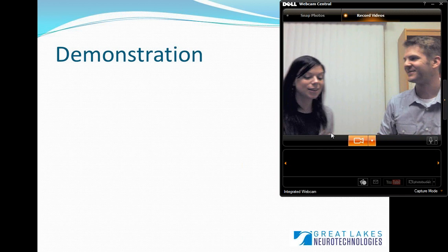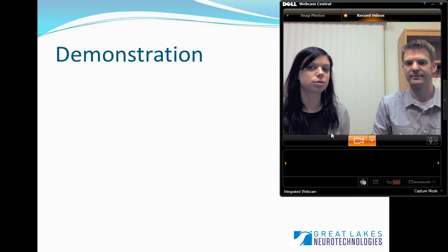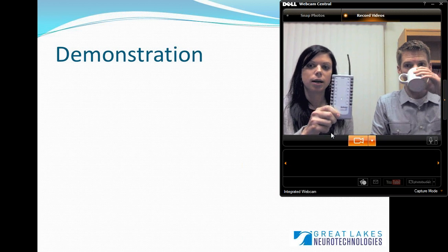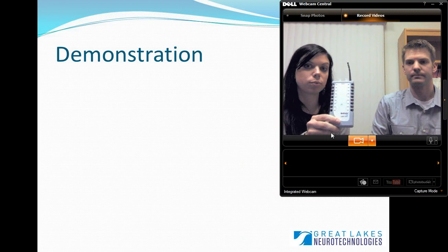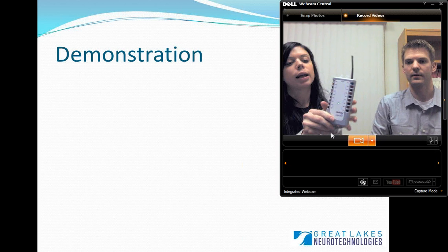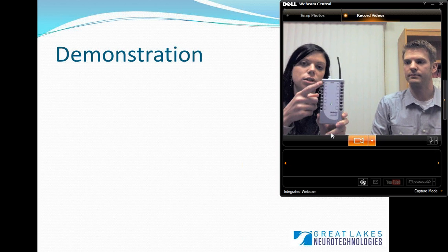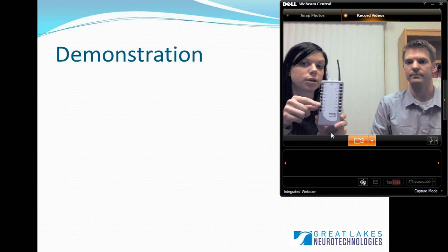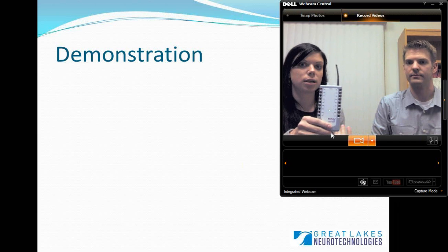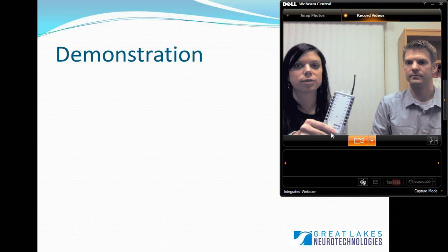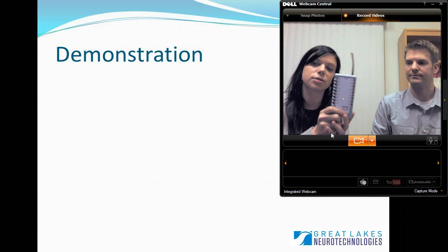Okay, thanks, Eric. I'm actually going to now show a device that we manufacture here at Great Lakes Neurotechnologies called the BioRadio. This is the BioRadio right here. It's a wireless 8-channel programmable monitor. And kind of going back to something that Eric mentioned earlier in the presentation, the 8 channels that you can see here on the front are differential inputs, all referenced to one ground. And you can program different parameters on each one of those channels to be appropriate for measuring different physiological signals. And I'll show that in more detail in a minute.